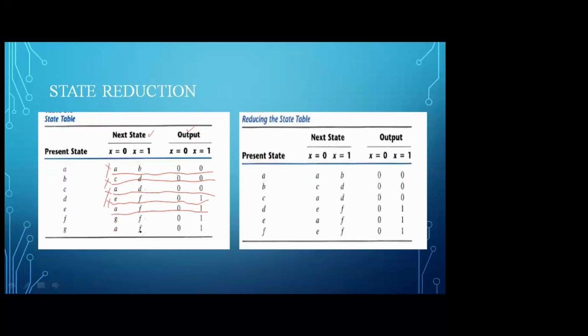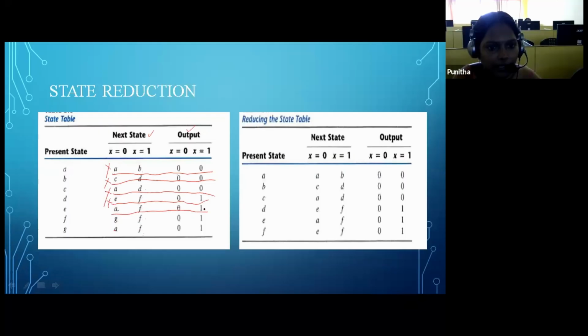This AF is present, and AF01 I need to look at, the full thing. AF01, AF01 is present. AF01 is present again. Then GF, is it present or not? I'm checking. Yes, next line GF01 is not present. Okay, the repetition in the states is this one. AF01, AF01, this state is repeating again. So I need to eliminate one state.